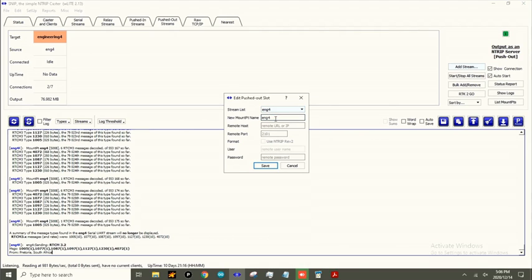And then for the mount point name, that refers to the mount point which you registered with the service. In our case, it was again RTK2Go. So we will call this engineering 4. Then the remote URL or IP will be www.rtk2go.com. The port is 2101.